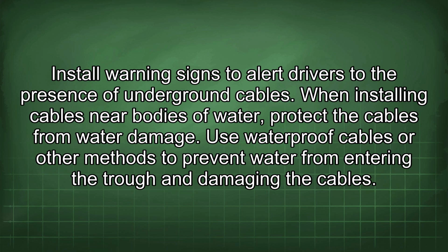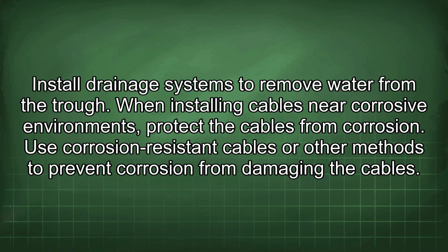When installing cables near bodies of water, protect the cables from water damage. Use waterproof cables or other methods to prevent water from entering the trough and damaging the cables. Install drainage systems to remove water from the trough.